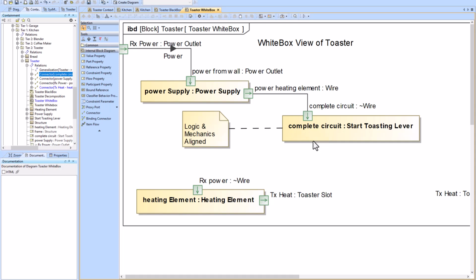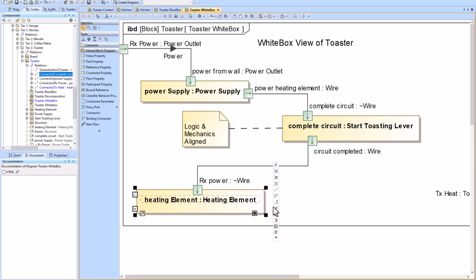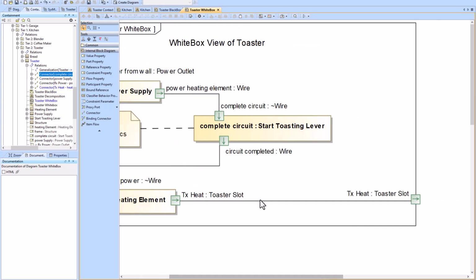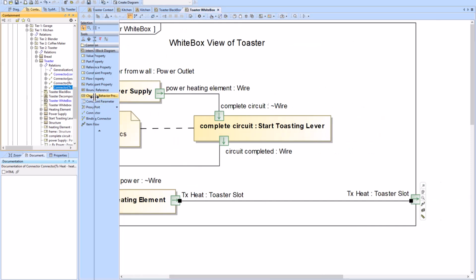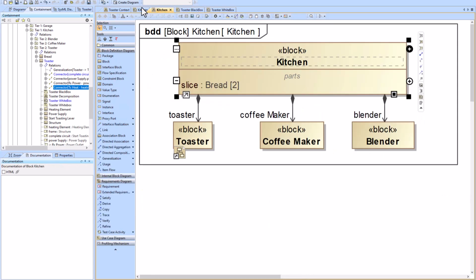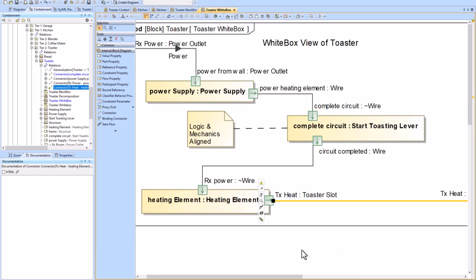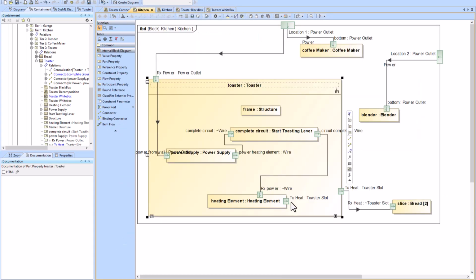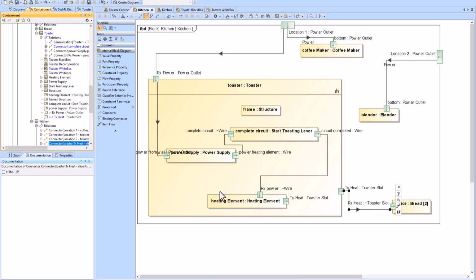And to get those wires to show back up, you can just show the proxy ports and they'll pop back. So I'll do that for this one as well. And now it's popped back, but notice this one will turn orange. There we go. It just took a second to get it to turn orange there. Let's say that it was incorrect and that connection was wrong. We would hit delete connector, and now it's gone there, as well as the upper level right here. It's not there.